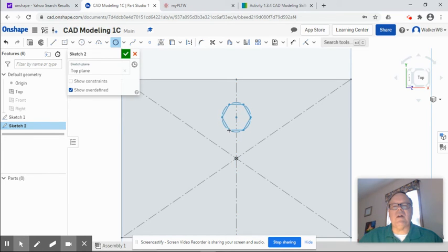And I'm going to pull it away and sort of let it sit in here flat like this. Now, you'll notice every time you do a polygon, it starts out as a hexagon, but we can change that. Once I click, I can actually drag in or out and make it more or less sides. So I'm going to make it a 5-sided pentagon. Click again. And now that I have my pentagon on the vertical line, I need to make it 0.35 on the dimension. So I'm going to hit escape.